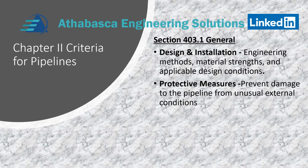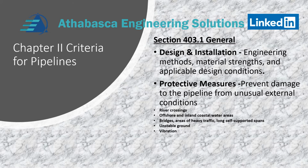Next thing is protective measures. Protective measures to pipelines from unusual external conditions must be considered in the design. These include items like river crossings, offshore and inland coastal water areas, bridges in areas of heavy traffic, long self-supported spans, unstable ground, vibration, weight of special attachments, forces resulting from abnormal thermal conditions.